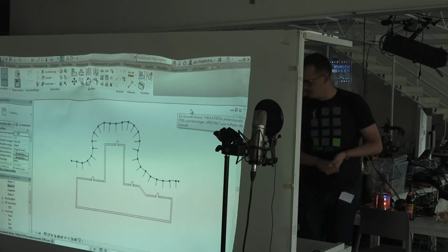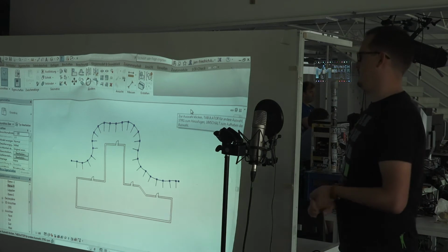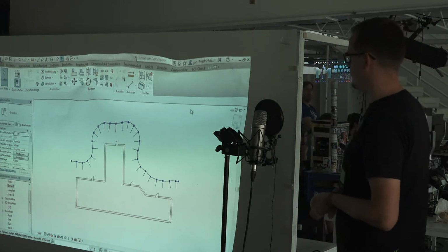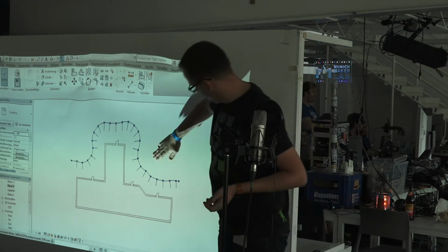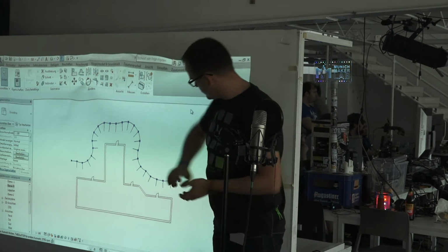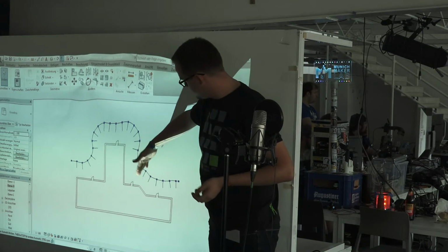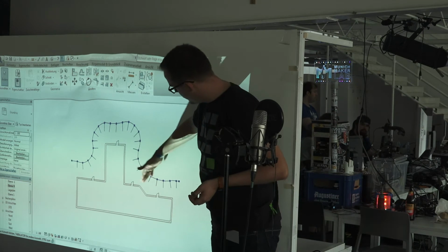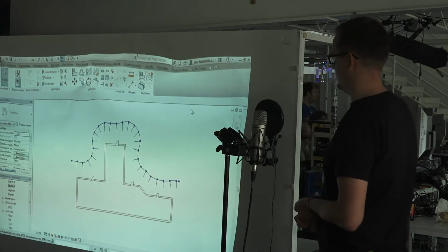Then you can see the result from the top view, which from our view is the best path the drone has to fly to make good photogrammetric results. As you can see, the idea is that these are the points where the drone shoots the photo, and each point has a direction, the drone's heading, and has to be oriented as a normal to the surface which is covered. This is the general constraint.